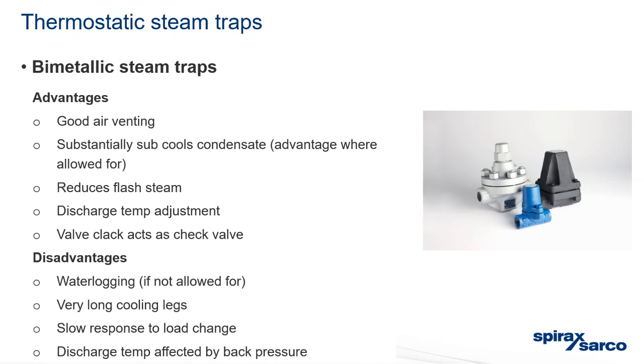Okay. The more steam traps you put in, as long as you don't put them every 10 meters, the drier, the more usable your steam is going to be. So yes, as we said, every 30 to 50 meters.